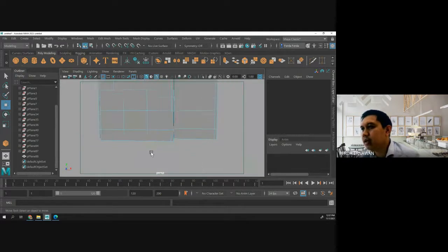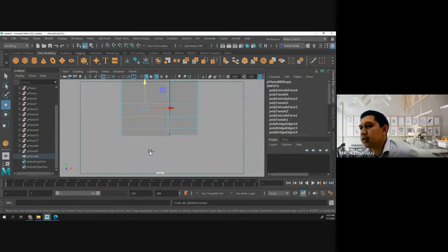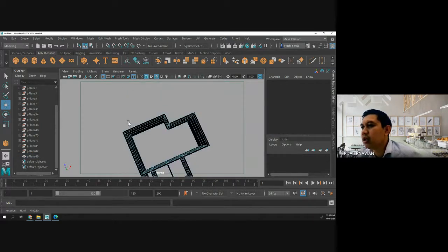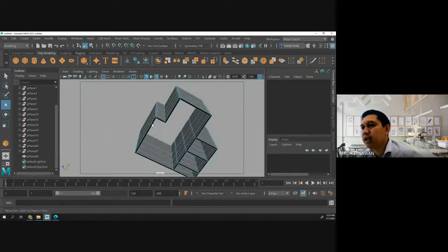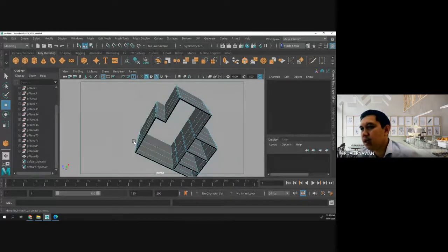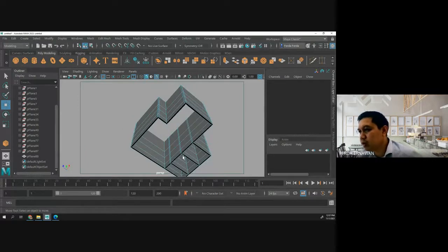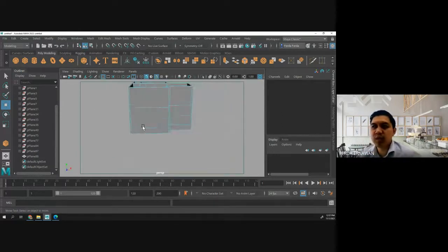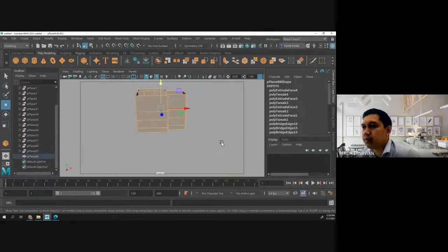So let us repeat again. Control Z, Z again. So we have to do this one first. Fill the gap first. How? This is face, isn't it? Right click, face. Are we going to select one by one? Yes, you can do that. But I will not do it one by one because there are too many here. There is a small rectangle here. What happens if you have a large building? It takes time. So I select all, but I select face first.